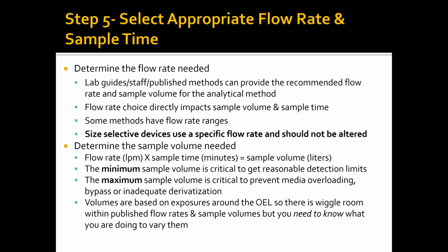All these methods have a minimum volume. You want to observe that because otherwise you're going to get some terrible detection limits that limits your interpretation. And on the opposite end, if you go beyond the maximum volume, you could get media overloading. This is not a problem if you're expecting low exposure limits and you can kind of exceed the maximum volume. There's some wiggle room, but you need to know what you're doing.